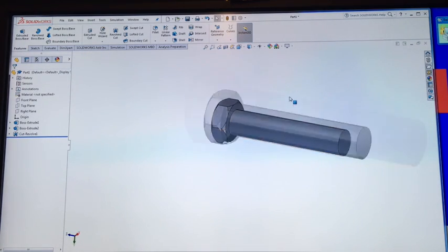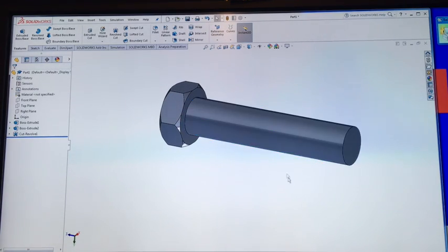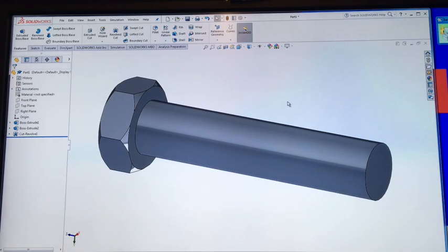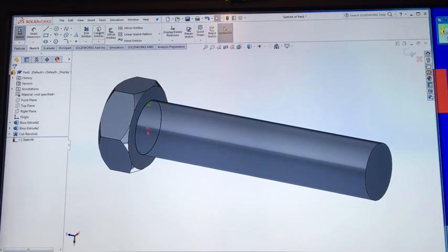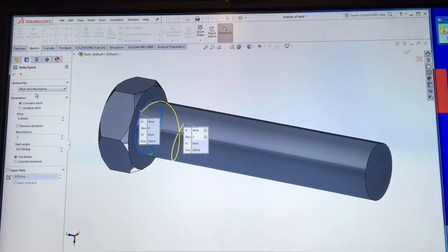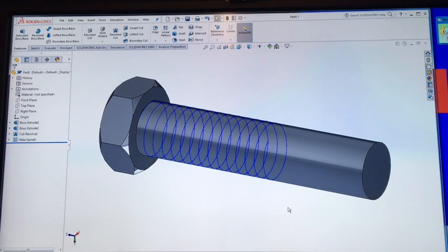Okay. All right, the other one we're going to do is a thread, down the length of this. Now, it used to be that to do a thread, you would create a helix and spiral from this face, and you would set height and maybe revolutions. So you create the spiral. Now this would be a curve. We haven't gotten to curves yet, but a curve is basically a line in space that you can then use for something like a sweep.